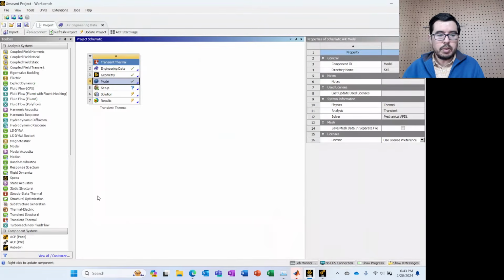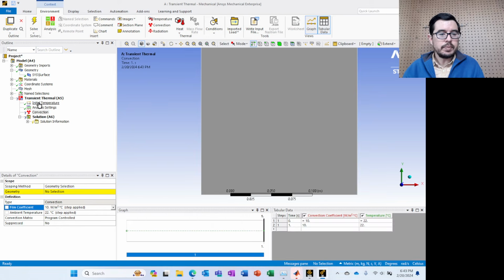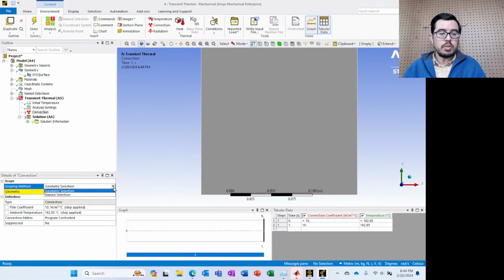So we're going to come over here and we're going to put in, I can't even remember, I just forgot the number, 162.85. All right, so 162.85. Where's that? Free stream? Yes, 162.85. Okay, so now that's in. But we haven't selected where this is applied. Well, remember we named those selections, so we can go to name selection, and we can then come down here,